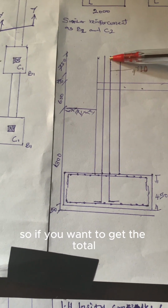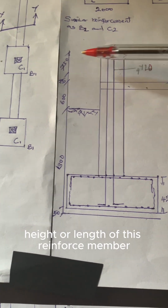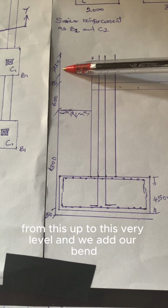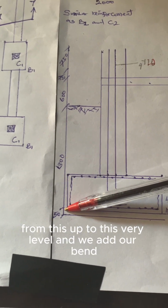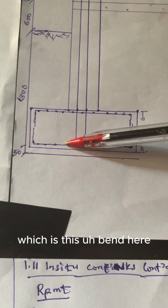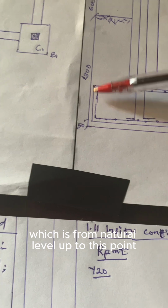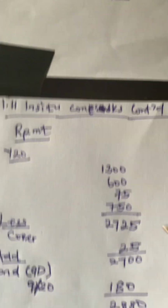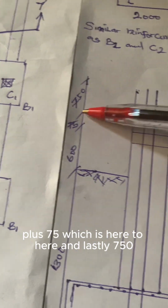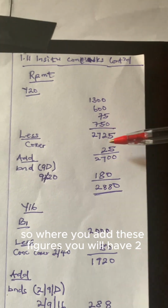So if we want to get the total height or length of this reinforcement bar, we add from this up to this very level, and we add our bend, which is this bend here. So we go ahead to add 1003, which is from natural ground level up to this point, plus 600, which is from here to here, plus 75, which is here to here, and lastly 750. So when you add these figures, you will have